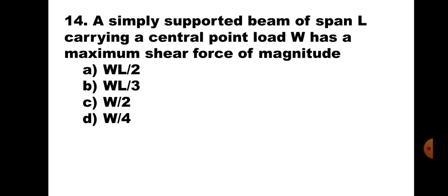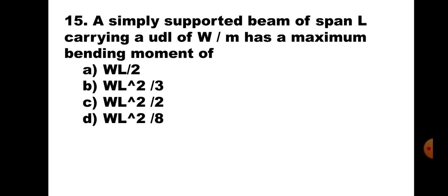Question number 14. A simply supported beam of span L carrying a central point load W has a maximum shear force of magnitude. This is a standard case of a simply supported beam carrying a point load at center. The maximum shear force will be the reaction, that is W by 2. Hence the correct answer is C, W by 2.